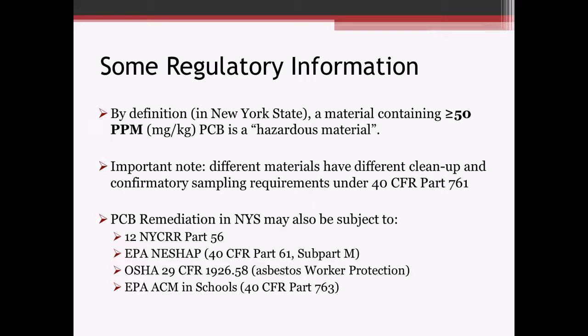All right, some more regulatory information. I mentioned earlier, greater than or equal to 50 parts per million PCB is regulated as hazardous material here in New York State. Important to know is that different materials have different cleanup and confirmatory sampling requirements under the PCB Mega Rule. So it depends on what you're dealing with and how you address the cleanup.